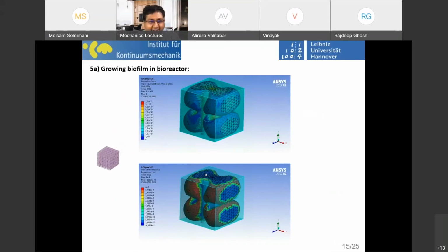And since we are talking about these soft materials, aren't they viscoelastic, or do you think that would make any difference? Yeah, absolutely, you are right, Ajay. Right now, the viscous effects are completely excluded from the model. But one of my directions for extending this work is exactly viscoelasticity. Maybe we start with a linear viscoelastic framework that is easier, the Prony series, which you know better than me because it's your field of expertise. Then of course we need to introduce a new relaxation time to characterize that viscous effect.